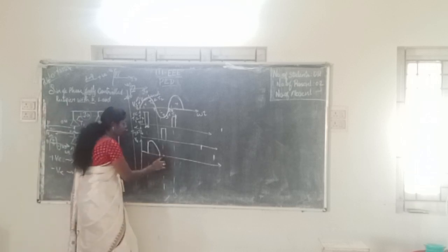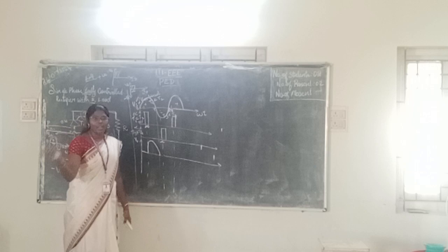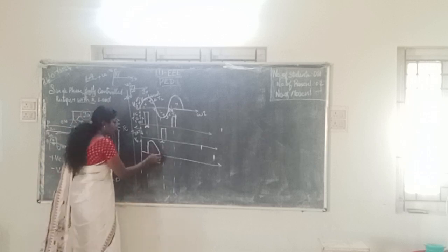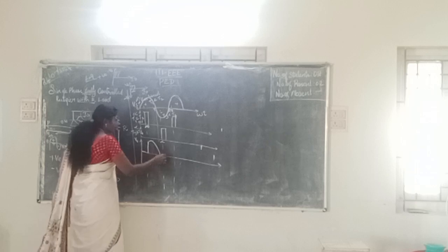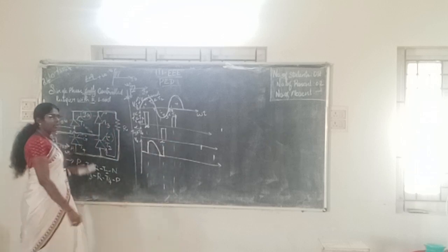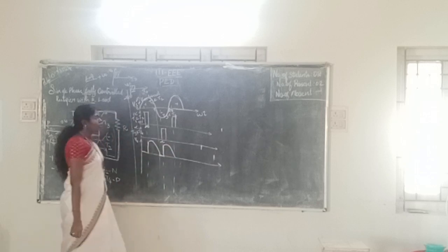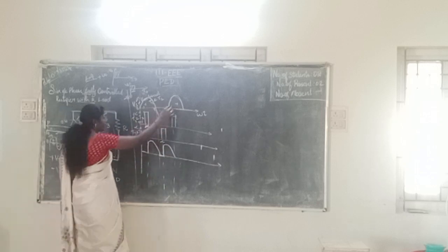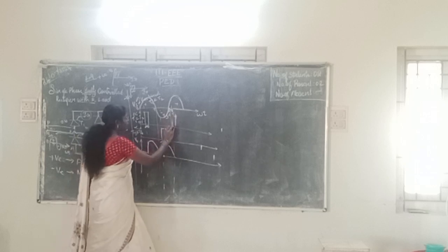Again during the negative half cycle, one more alpha signal is given to the thyristors T3 and T4. So at that point it will remain 0. After that, once T3 and T4 turn on, the voltage will flow again till 2 pi. This is the alpha.